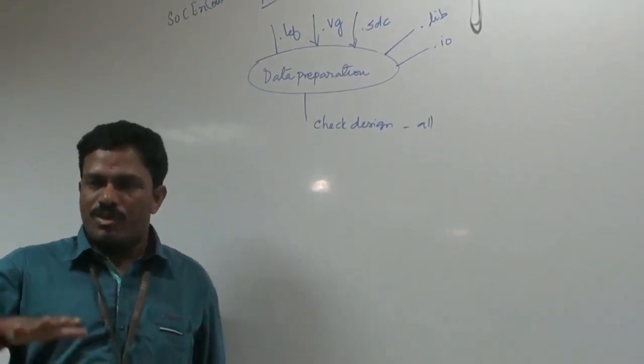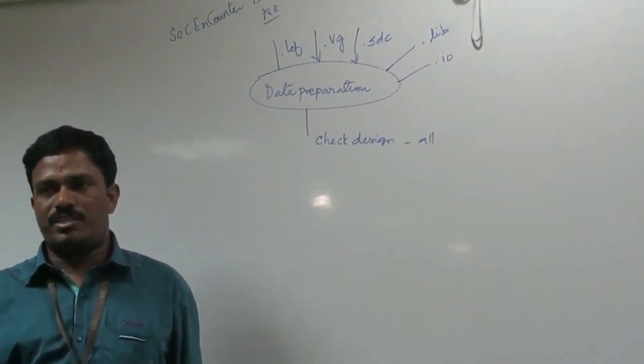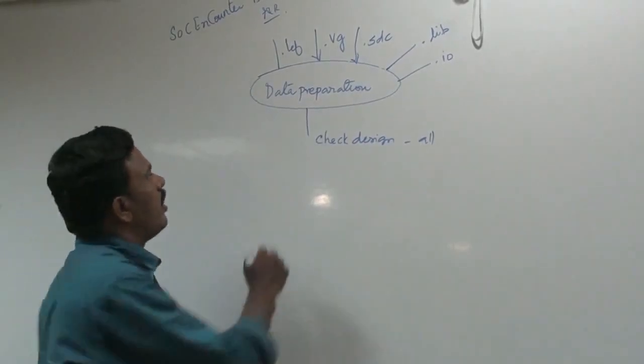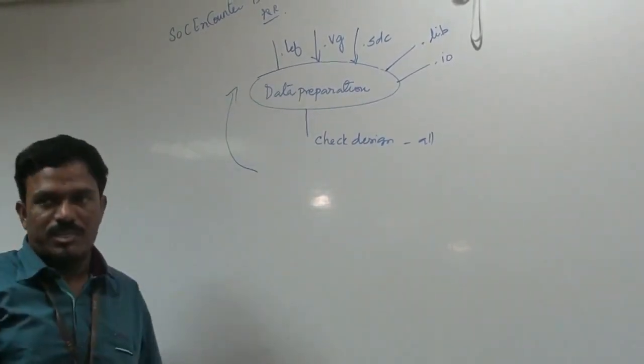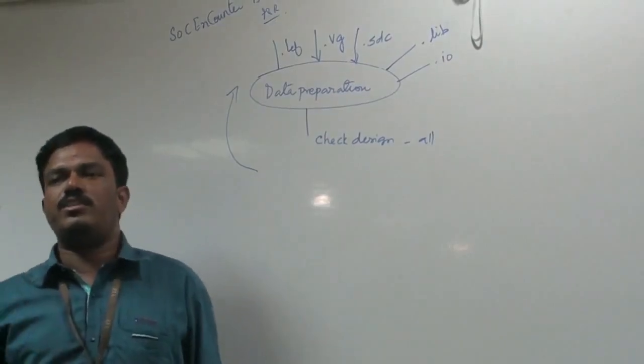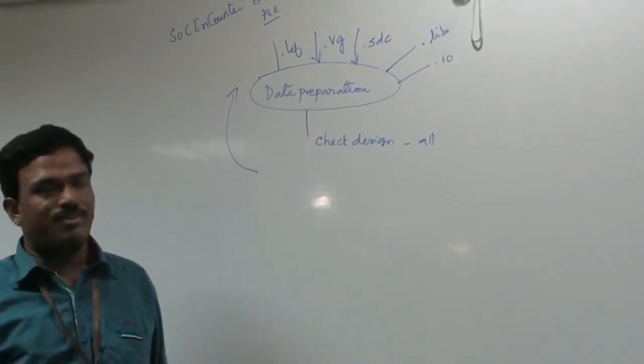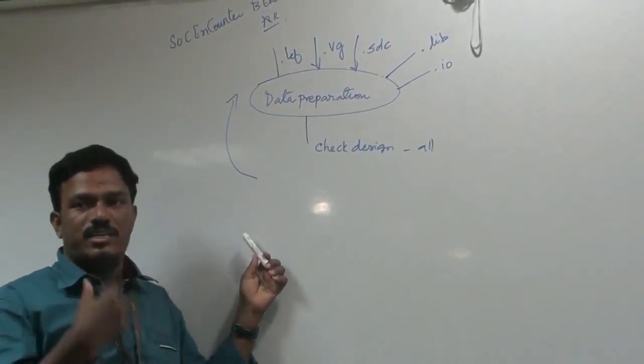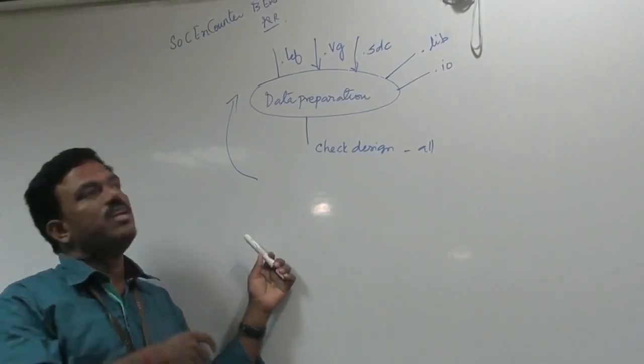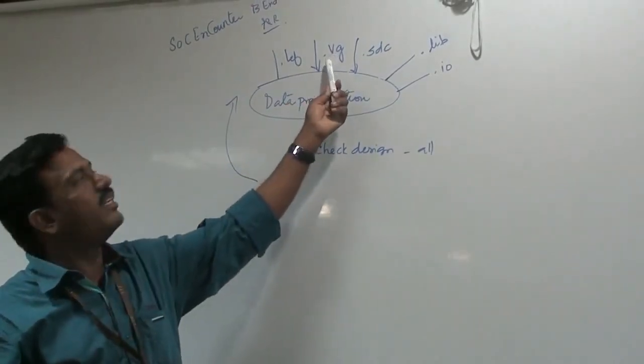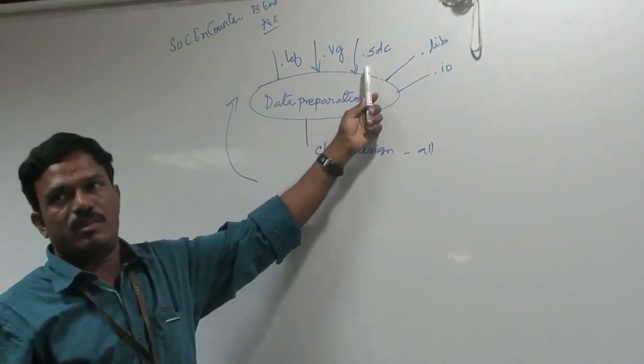Everything you will come to know. Whenever you find a difficulty or any other issues, we need to tell the RTL fellow that there is a bug in RTL, correct it and give it to me, right? So that fellow will take care of your RTL and you just do some optimization. Again, he will give you the gate level Verilog netlist as well as SDC.